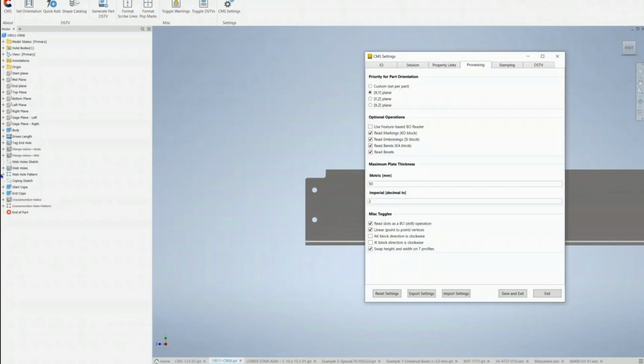The reason why I'm telling this is because of the technology that we are using to detect our operations. So you're allowed to suppress any components that you don't want. If you suppress anything, it's going to be gone from that face anyway, right? So when the software is analyzing the face, it will not see those operations, so it will not bring them into the NC1 file. So again, if you have suppressed members or suppressed features, they will not show up in the NC1 file.